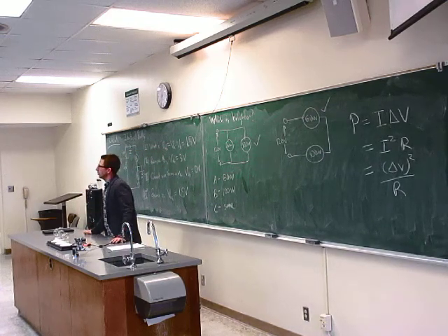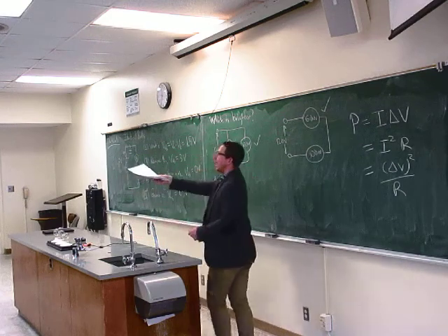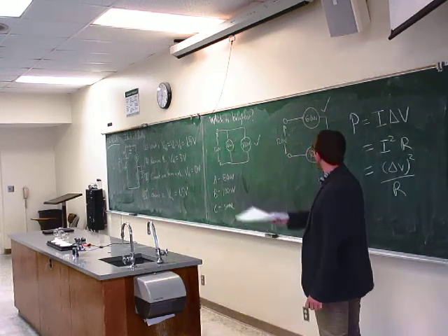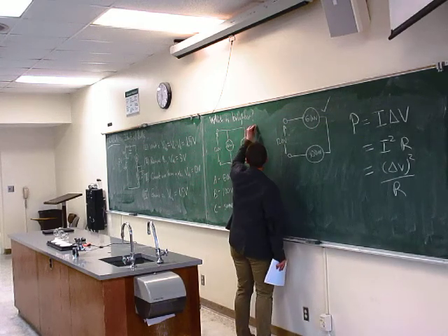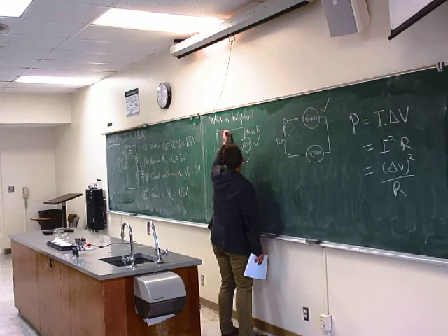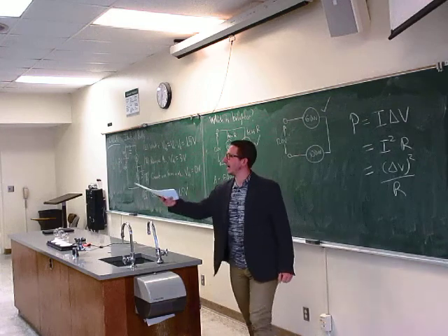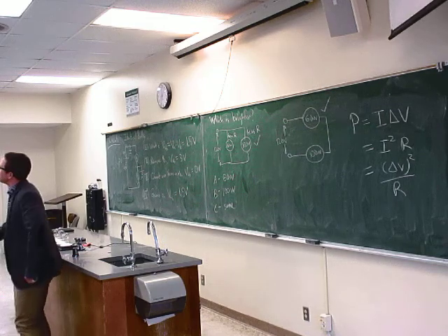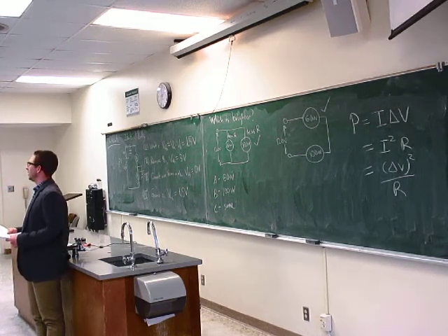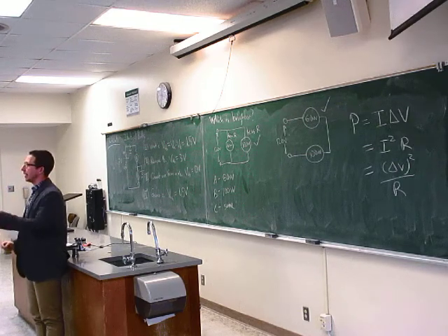Yes. So how do we know that the 100 watt one has more resistance? Well, sorry, hang on. The 100 watt has less resistance. So this one has less R, doesn't it? That's what we found. Less R. This is more R. Well, the point here is when you buy a light bulb and it says 100 watts on it, you're probably not thinking about what the resistance is. So a higher wattage bulb has a lower resistance. That's the key takeaway here.